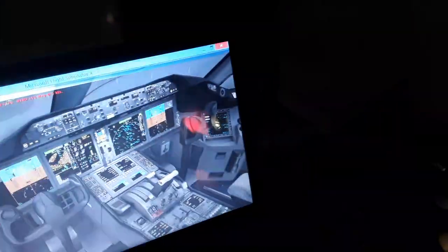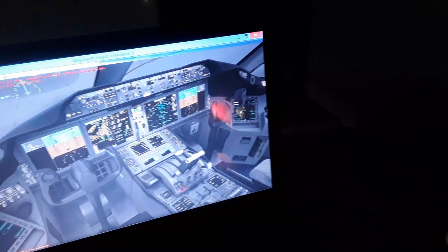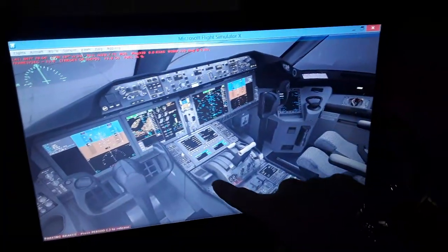So sometimes it's not actually in the same way as you deflect the flight controls, as the flight control surface deflects is controlled by the fly-by-wire system, the flight control computers, unless you are in the direct mode. So you have the horizontal trim stabilizer, as I told you. You have the manual trim, also you have the alternate trim channel, and you have the auto trim channel.